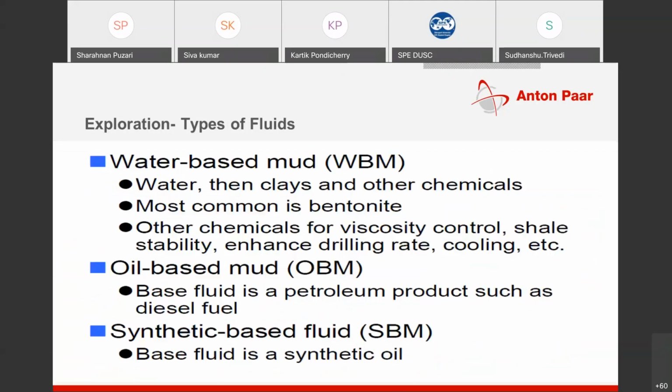When you are exploring, there are three types of drilling fluids: water-based mud, which you call WBM, oil-based mud, and synthetic base fluid. So WBM, OBM, and SBM are the three kinds of fluids. WBM is basically water, then clay, and other chemicals.